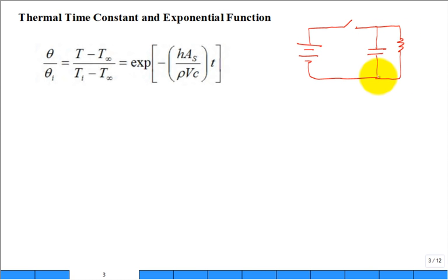So initially, the switch is closed, so the battery can send electric current over to that side. And what happens is after a while, initially, it really starts flowing through the capacitor a lot. But after a while, the capacitor builds up voltage. There's a big voltage across the capacitor. And what happens is the current no longer goes through the capacitor to charge it anymore. It just goes only through the resistor. True? That's all to get the system set up.